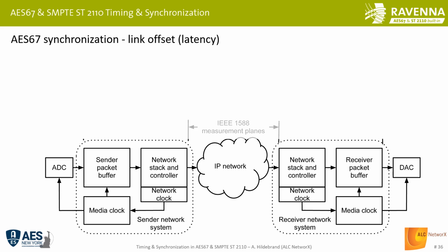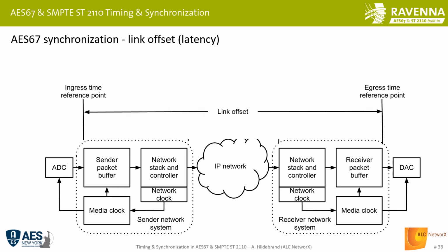But for our link offset and playout discussion, this is of no means at all. So I delete them from the picture again. And our reference time planes are the ingress time point, the egress time point, and between those is the link offset. That means the exact time when I take a sample in, or ingest a sample, and the time when I want to play out a sample or forward it to the next processing stage. That's called the link offset. These are our reference time planes.